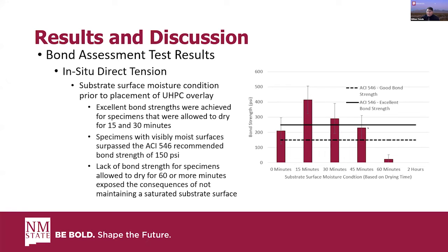250 PSI. And as you can see, specimens allowed to dry for 15 or 30 minutes were able to exceed that 250 PSI recommendation. And specimens that were visibly moist, or dried for 45 minutes or less, were able to exceed that 150 PSI minimum recommendation for adequate bond strength. And specimens that were allowed to dry for 60 or more minutes did not achieve adequate bond strengths, not even close to achieving it.